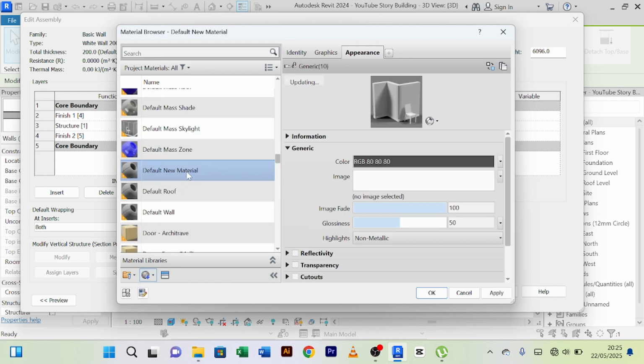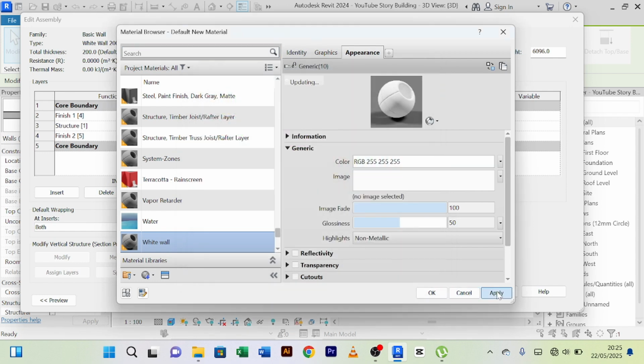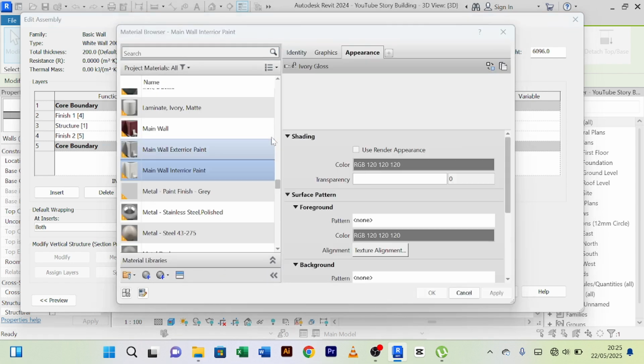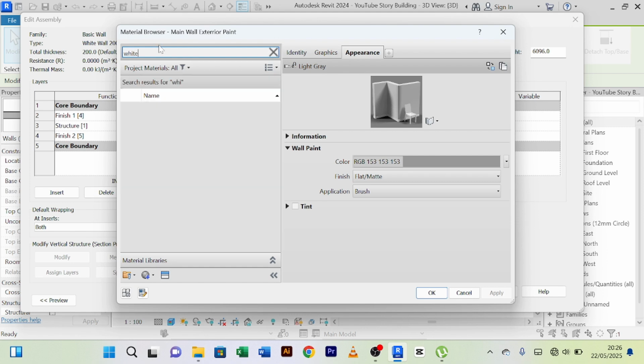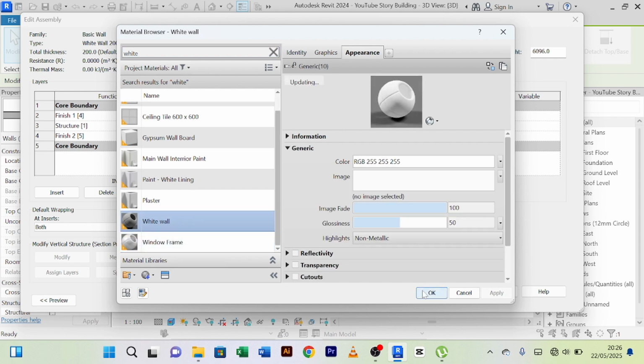Then we can select this. Then we come to our wall. Of course, when we select the wall, it will show you you are now in the wall category. You can click on the drop down and look for your white wall. It is here. That's what we want, even for this, because they are all in the same place. So instead of doing this manually, you can just come to your match type property. You click on this, you match it with this. It's saying can't make wall. Okay, so we're going to do it manually.